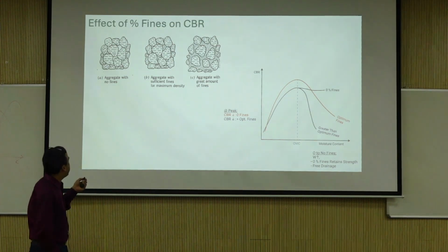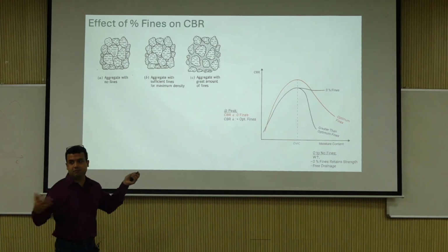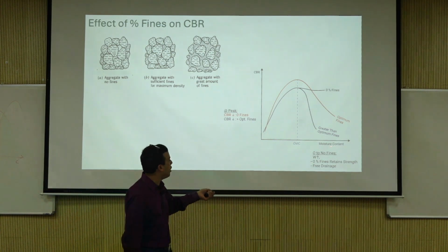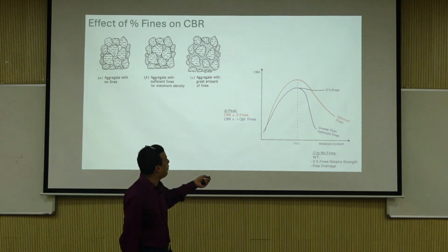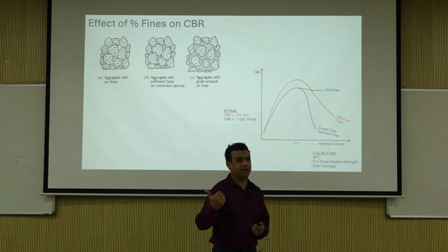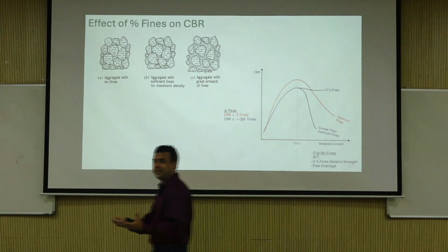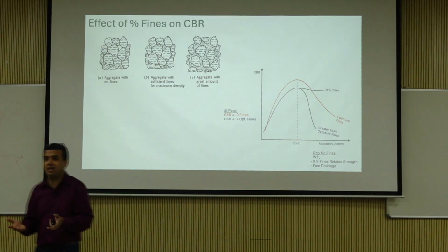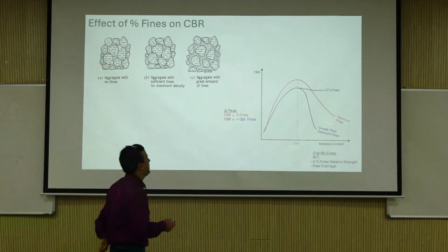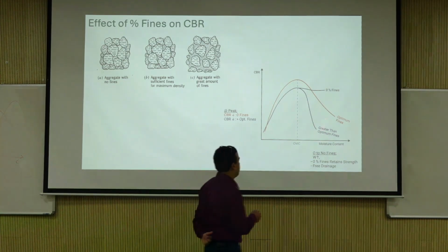Fines matrix, you can have no fines, just the right amount of fines, and a greater amount of fines than optimum. Moisture content, at a certain point, if there is no fine, the water you add, what happens to it? It escapes. So your material or your sample does not really change behavior because the water is gone, right? So it's very important to realize where you have optimum fines or greater than optimum fines.